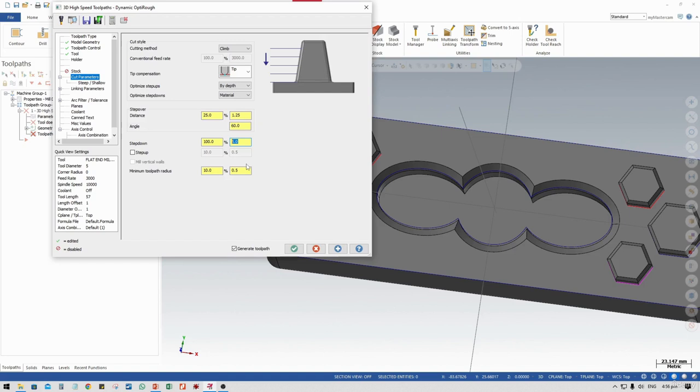So let me define that. I'm going to make a cut of 2mm each time. And there is an option here in the step down, that is step up. Step up means that the distance between step downs is 2mm, but every 2mm, how much step will it take? 0.5mm. This is what we tell it, that it will take a minimum amount of cut every time between two cuts. So it gives the cutter a light in-place movement and gives the cutter finishing to the workpiece and gives no precise chips. So these are the cutting parameters we have done.